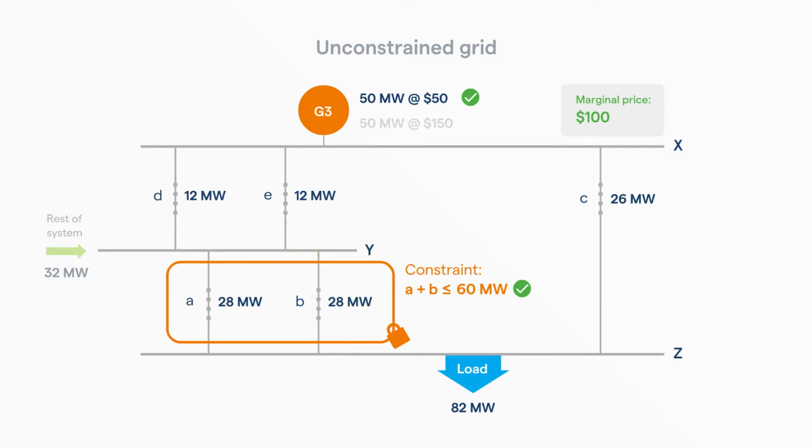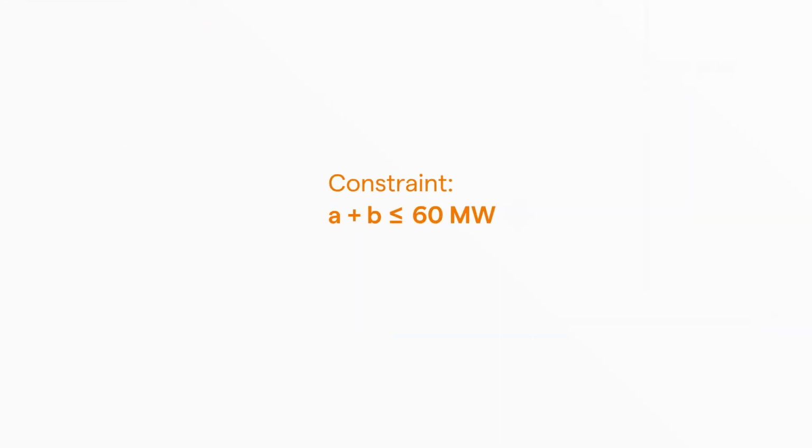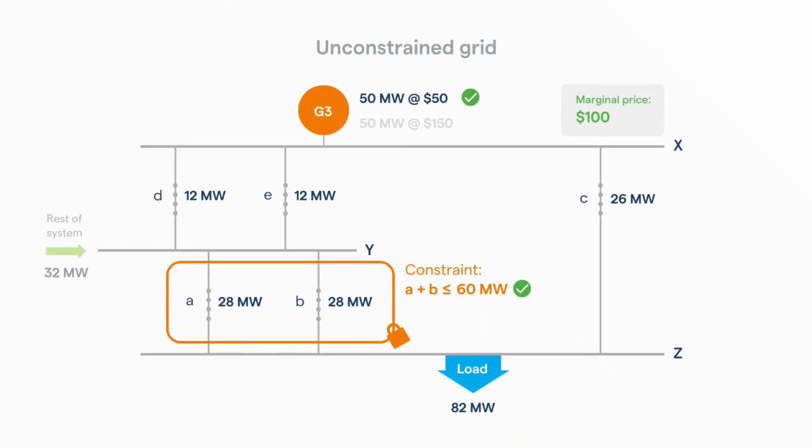Constraints are based on modelled power system conditions. Forward schedules show when the market expects constraints to apply and the limit. In real time, system conditions may be different, so constraints may need to be adjusted to resolve real-time violations. As a result of a real-time adjustment, there will be change to the generation pattern compared to what is forecast in the forward schedules. The constantly changing power system means system coordinators regularly monitor the right-hand side of constraints to ensure accuracy. In this case, a real-time N-1 violation exists.